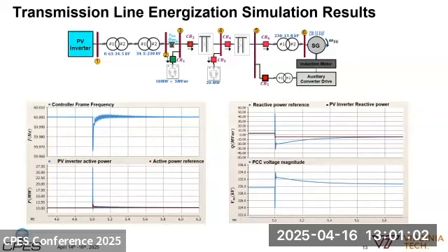And if we take a look at the simulation results measured at the PCC of the inverter, we see that it can withstand the fast power surge. And also it is able to decrease its Q injection to meet the load side demand change under the overvoltage dynamic. At the same time, the frequency and voltage can be kept in a range close to the nominal values.